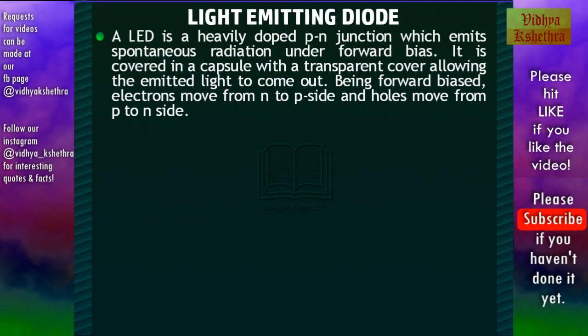Now, the light emitting diode. An LED is a heavily doped PN junction which emits spontaneous radiation under forward bias. It is covered in a capsule with a transparent cover, allowing the emitted light to come out. Being forward biased, electrons move from N to P side and holes move from P to N side.